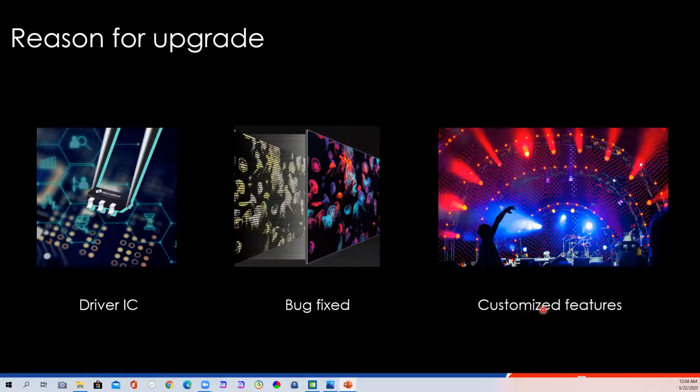For the first one, the quality of the driver IC will greatly affect the performance of screen display. Different LED manufacturers will choose different driver IC for their products. Many driver ICs have their own working principles and special drivers. In order to let those drivers work properly, firmware plays an important role. Currently, the IC classification on this market is mainly divided into two types, the PWM driver ICs and normal ICs. Different firmware for them.